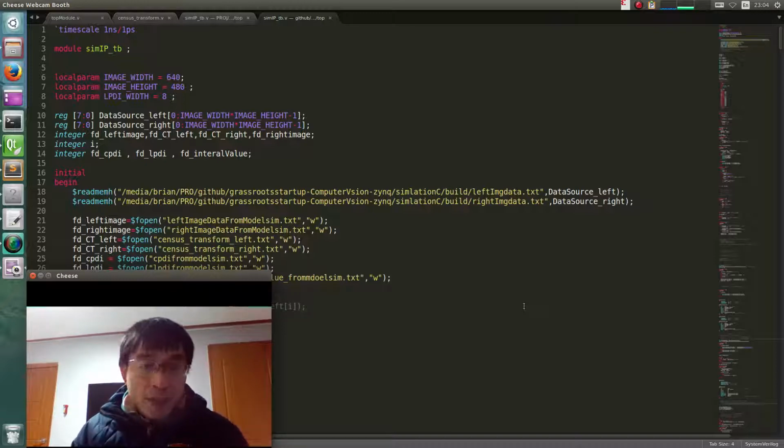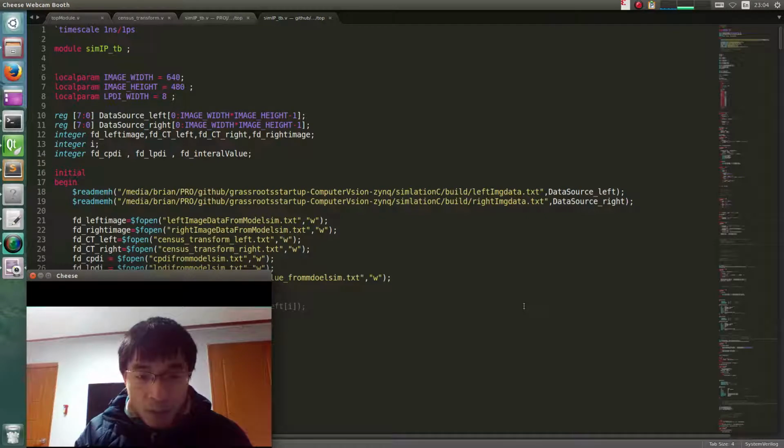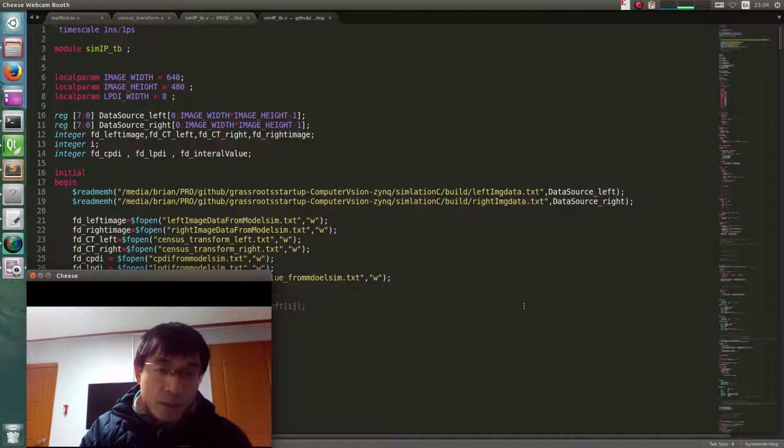So writing synthesizable code is very important, right? You cannot think like a C programmer or other programmer. You have to think of yourself as writing hardware code, giving instructions to the synthesizer tools on how you want to organize the registers and flip flops. Also, in the FPGA, a logic gate is a lookup table.